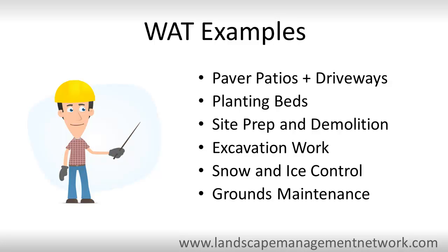Even general conditions are a good example for a template. Build a template that includes all the little things that might get missed when estimating a job. Permits, delivery charges, temporary parking fees, temporary washrooms, any of these minor costs which might not always get used but always need to be thought about when you're pricing a job.